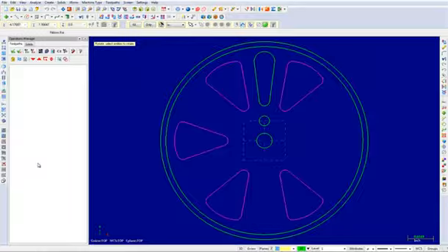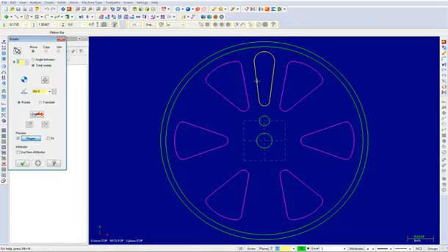From here, select the Repaint icon as shown. Your geometry will appear as shown up to this point. Next, holding the Shift key again, pick the following shape and press Enter. You will notice that the Rotate dialog box has appeared again. This time, ensure Copy is enabled and that the number of copies is set to 5.